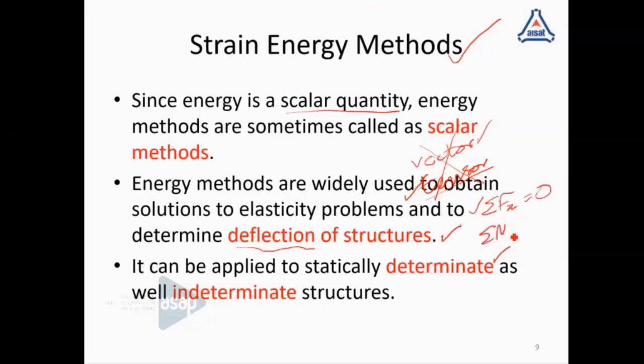And another equation used is sigma Mx, that is the sum of moments about the point x is equal to 0 in equilibrium. And if you are able to solve a problem using any of these methods, we can call it a statically determinate problem. And if it is not possible, then we call it statically indeterminate. That is, using the principles of statics, we can solve the problem in a statically determinate case.